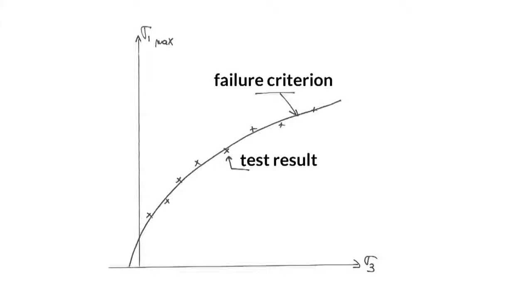Remember, we said in a previous topic, shear strength is not unique, but different tests should be performed at different confining pressure. When all these tests have been performed, we can plot the data as per the figure you're seeing now, and that gives us a failure criterion where we have all the shear strengths plotted against all the confining pressures. The general trend is a non-linear increase of shear strengths as we increase the confining pressure.